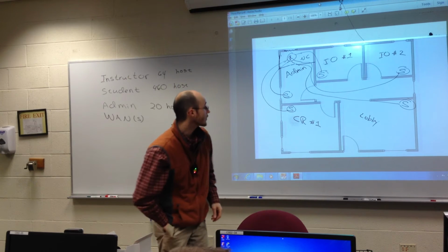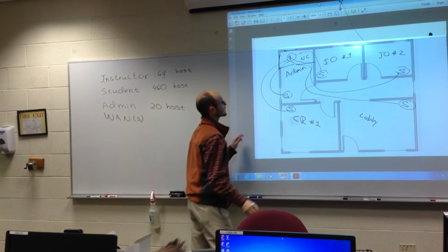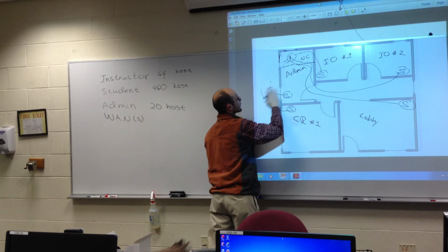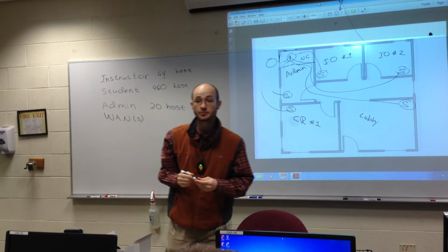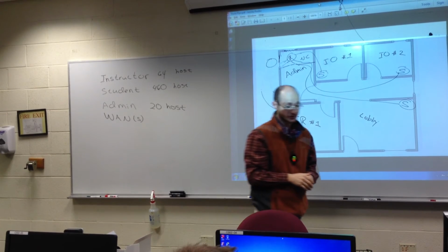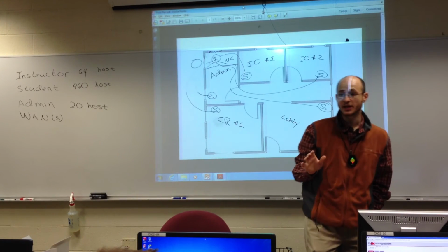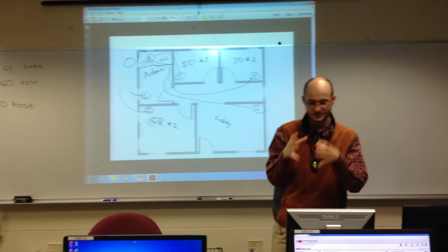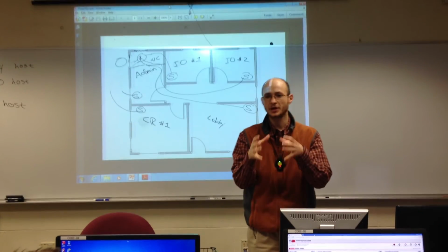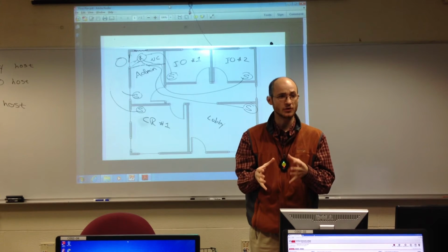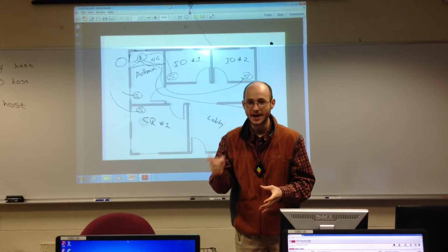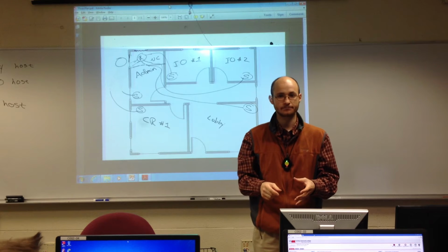Now, this is the thing I would suggest. When you're doing this, look at your wiring closet, and I would put a 6-inch PVC pipe, even in your house. If you are doing new construction or whatever the case may be, go get Schedule 40 PVC pipe, 6 inches, 4 inches if you have to, but 6 inches is what I'd recommend. Run it from your attic down to your basement.